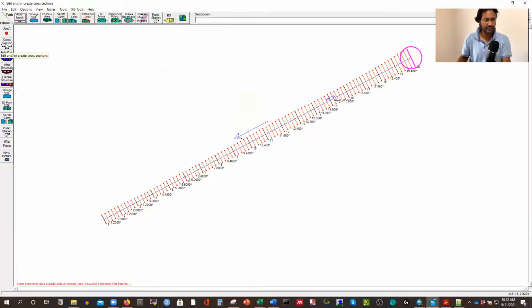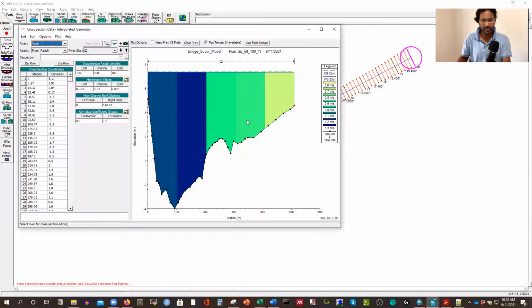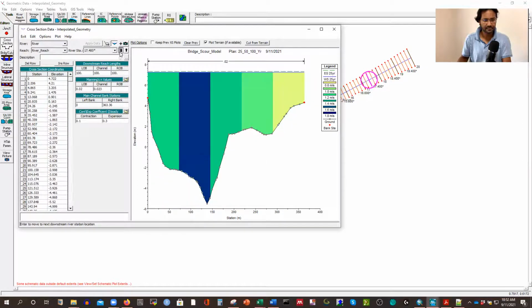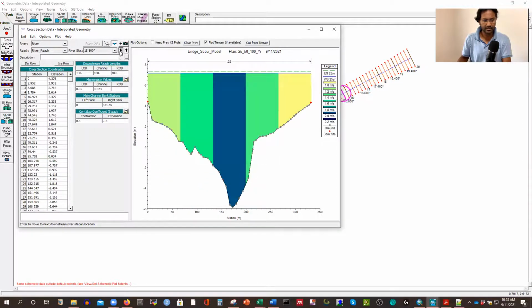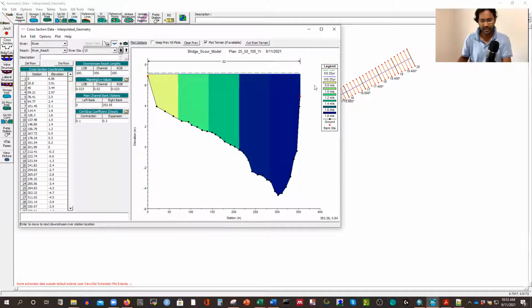I'm going to open the cross section from here. You can see it's pretty clean and nice. That is the most upstream section. You can see the velocity, right? On the outer bank we have the maximum velocity, and then if I go next, it's going to give us the flow rate. But the most important thing, can you recognize that? So we only have which one? Water surface elevation, that is right, 25 year.